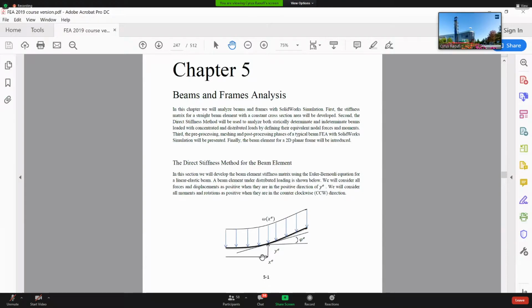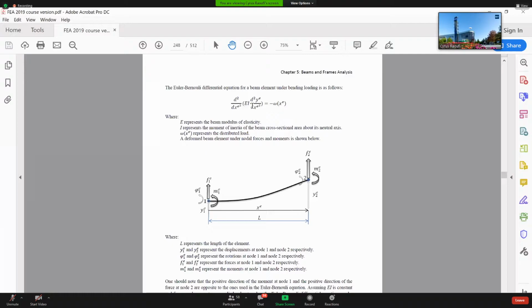However, for that function y, you can write the equation starting from the beam theory, which is called the Euler-Bernoulli equation. That's the governing equation. If the cross section is constant, EI times the fourth derivative of y with respect to x equals omega: EI d⁴y/dx⁴ = omega. You had this equation before in a different format, a different shape.